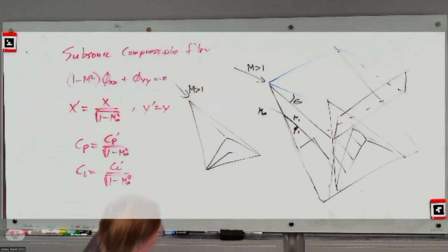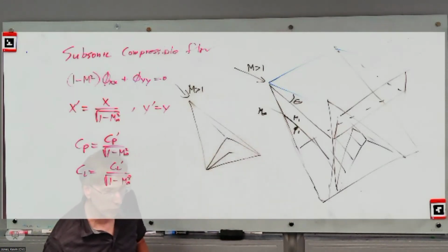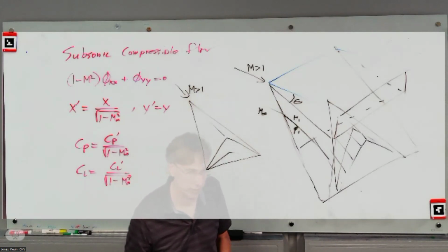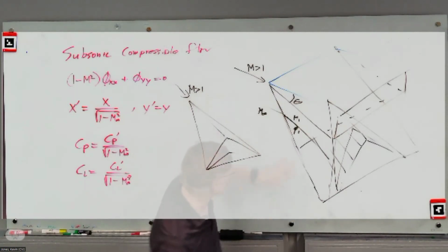Incidentally, this is one other thing we can point out here. What we're doing in CFX right now is what we call a shock capturing code. Before we get started, we have no idea where that shock is. We're using CFX to show us where the shock is. In this case, I know exactly where that shock is, and so I actually start my solution. I don't even have a domain outside of that shock.